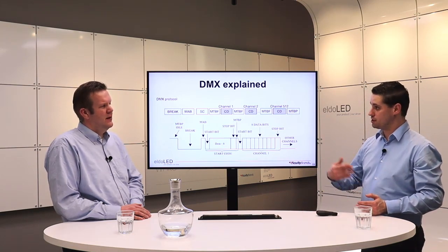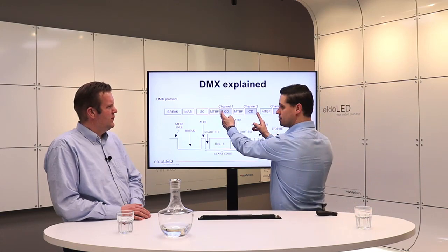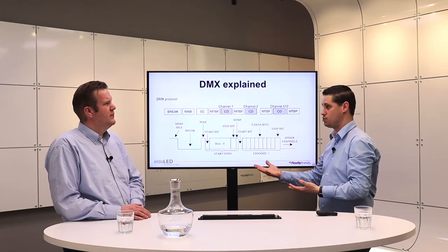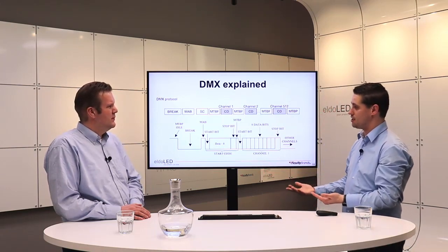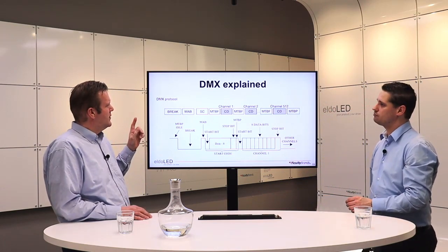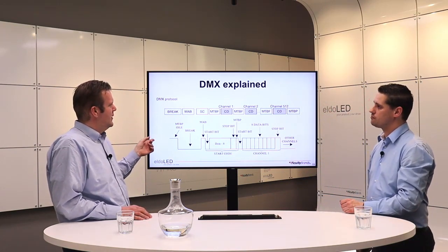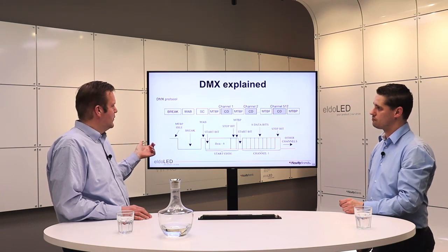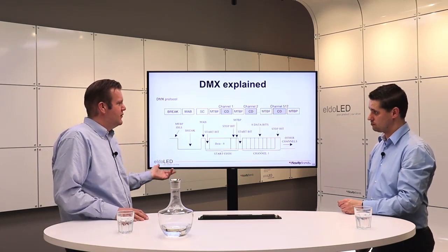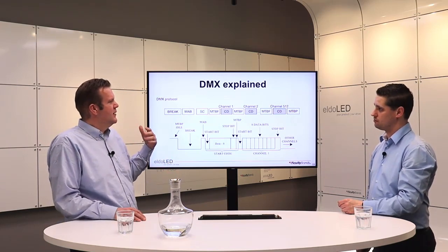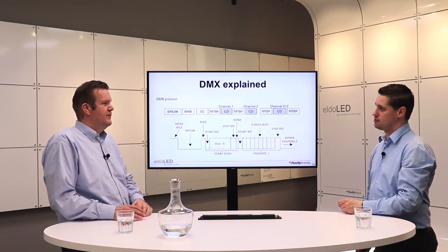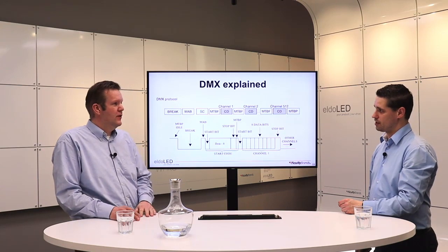Yeah, okay. But a single luminaire could combine 2 channels. Yes. Another luminaire can use only 1 channel on that same signal train. So you can mix that in the same data signal because that signal remains the same. Okay, so that means that when you are having a control desk, you have to ask the control desk, these channels I want to do on 16-bit, and these channels I have to do on 8-bit, and it's really important that you set up your driver accordingly as the lighting control desk requires. Indeed. So those 2 you have to match fully correct on the project.